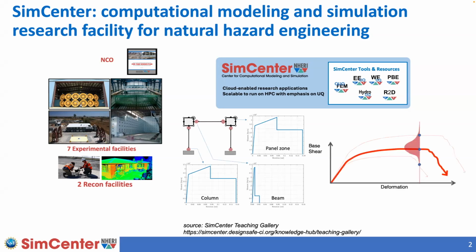And I also want to estimate a probability distribution of the base shear at different levels of deformation. It's not possible for me to build 100 RC frames, put them on a shaking table and test them. It's a huge waste of money and a huge waste of time. So this is when SimCenter software QuoFEM can come in and help me out.